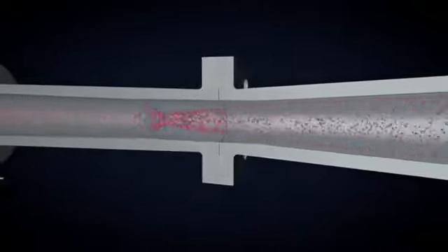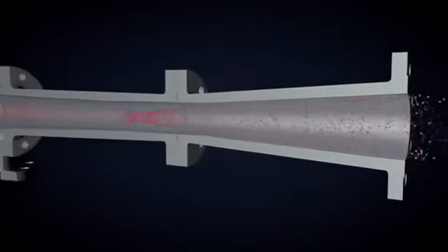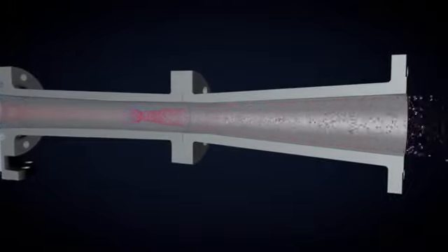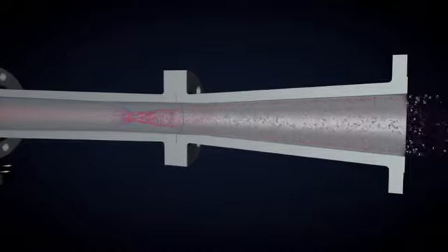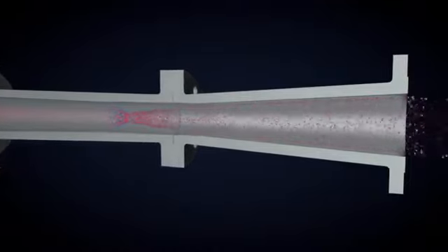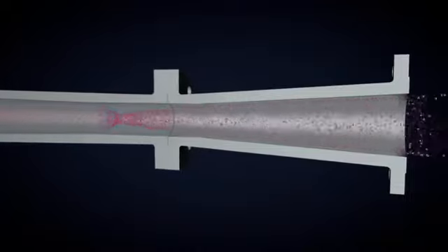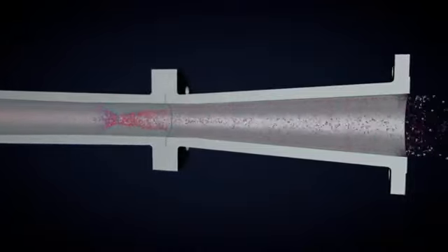The pressure is increased further in the outlet diverging section of the diffuser, where the subsonic mixture is slowed as cross-sectional area increases from the throat diameter to the discharge diameter. Slightly less than half of the total compression achieved in an ejector is obtained in the outlet diffuser section through simple deceleration of the subsonic flow.